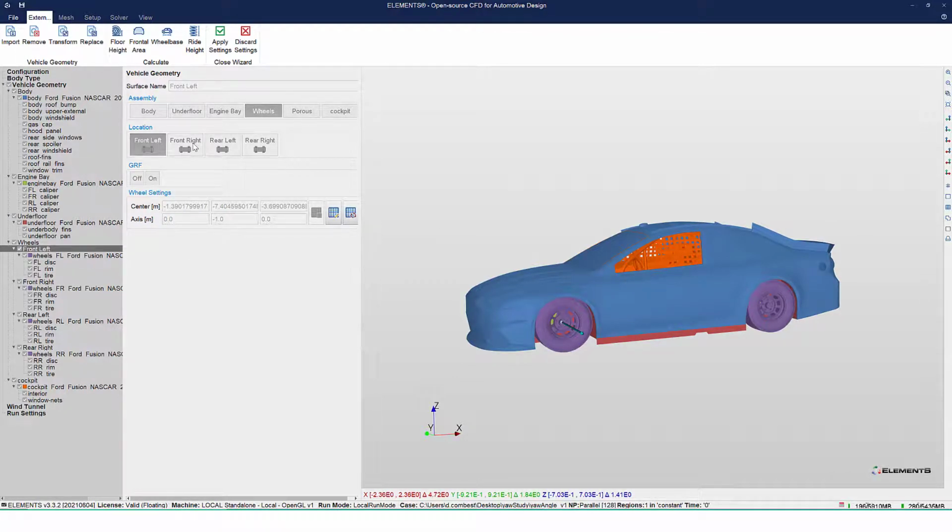It also does the task of determining where the wheels are with relation to each other in terms of front left, front right, rear left, rear right. And then it categorizes these different components. Now you'll notice that I have FL, FL, FL here. We can also prepend some of our STL surfaces to actually pre-categorize things when we bring them in. That's also a possibility. I've covered that in other webinars.